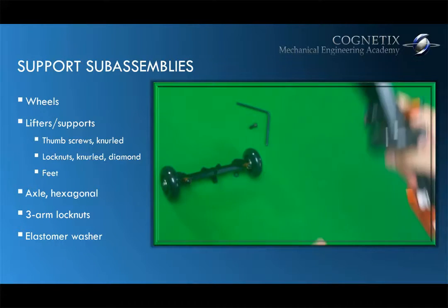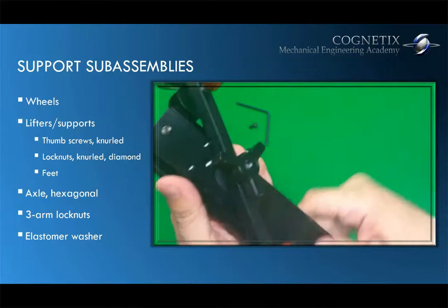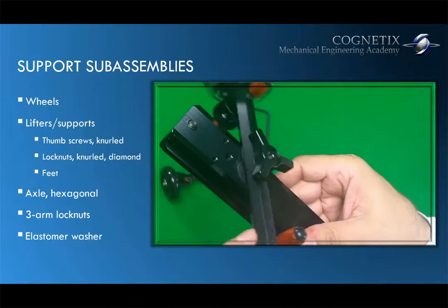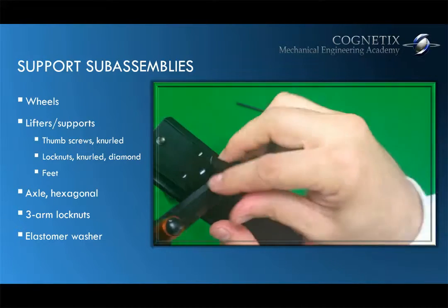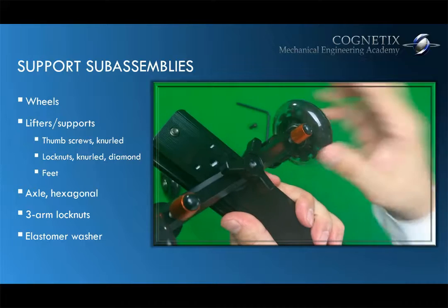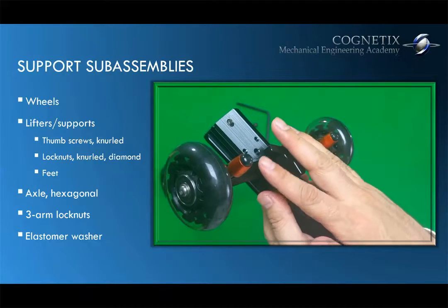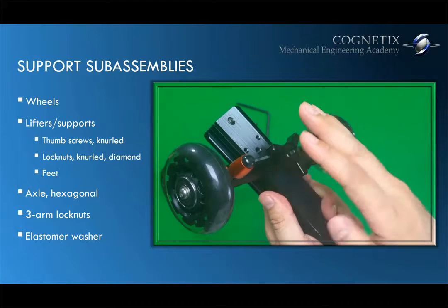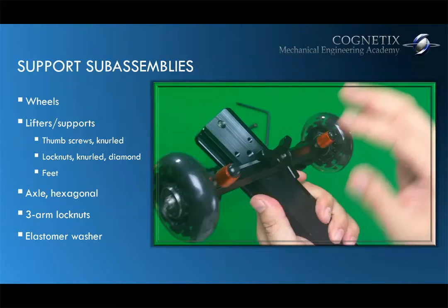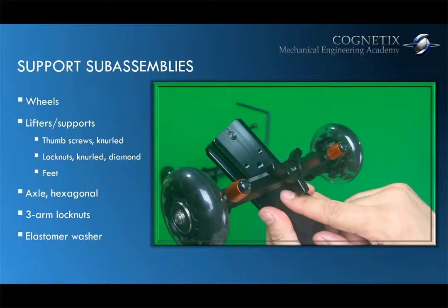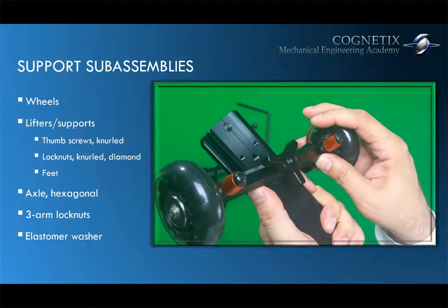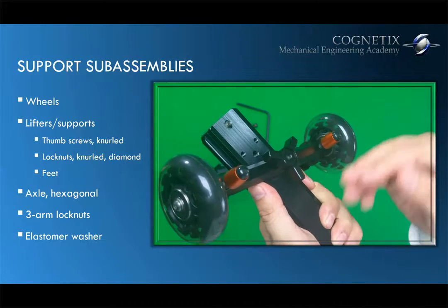And I imagine that the intent behind that, since this is adjustable as far as angles, and then you secure it again, having a flexible component right there keeps this from squeaking. Once you expose it to forces, if there's no elastomer material, it could turn a little bit and squeak and make a sound.